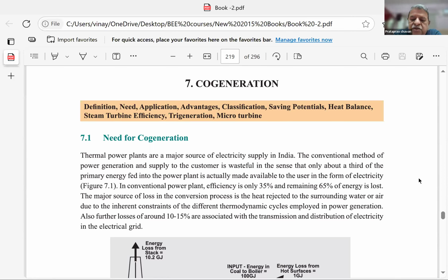Now, in this process, suppose they want heat at a pressure of 10 kg and a temperature of say 200 something. But then I will say that you are anyway burning fuel and generating steam. So can we divert part of the steam for electricity generation? Use a small reciprocating engine or a rotary turbine, generate power, and after the steam is taken out of the turbine at the desired pressure, the same steam can be used for the process.